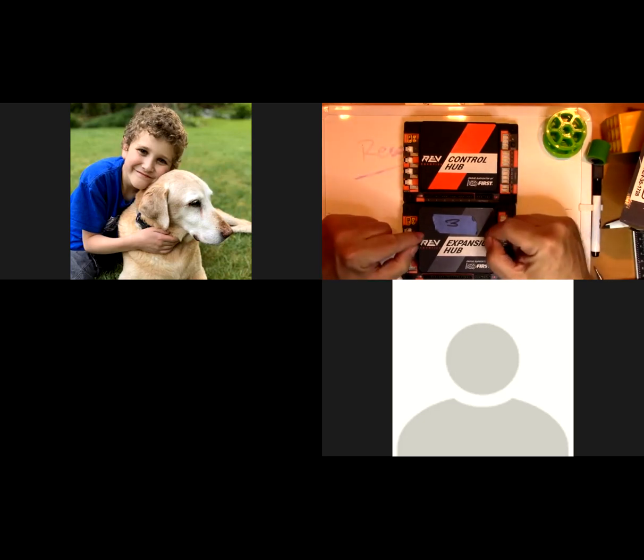In general, I would tell you that if you think there's any chance you're going to do Mecanum drives, you need to get an expansion hub because you're going to use up all of your motors on this. You can only put 1 motor per connection. Right. Okay. Make sense? Yep. Yeah. And so that's kind of the difference between a control hub and an expansion hub.